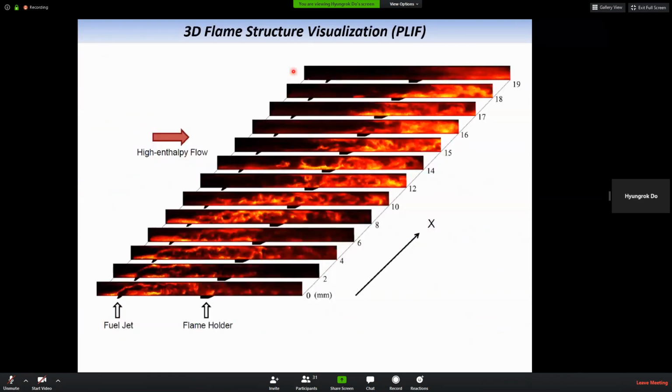But in this case, you are injecting the laser beam at 283.4, maybe 284 nanometer wavelength, and that photon energy will be easily absorbed by a very specific radical species, which is called OH, hydroxyl radical. And this OH radical is produced only in very high temperature reaction regions of the combustion reactions. Okay, so this is a kind of marker of a high temperature region, or the marker of the combustion reactions. Okay? Look at here.